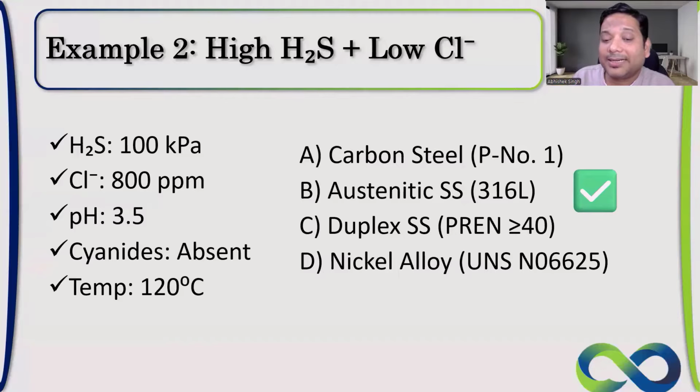Okay. Now what happens? Let us change the 120 degrees Celsius temperature a little bit. Let us make it 150. From 120, I have changed the temperature to 150. Now, do you think it can take 100 kPa partial pressure at that, even with a 30-degree variation? The partial pressure of H2S, you can see the limit. Notice the change.